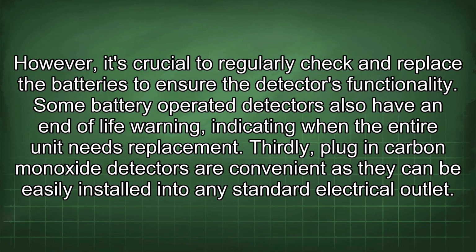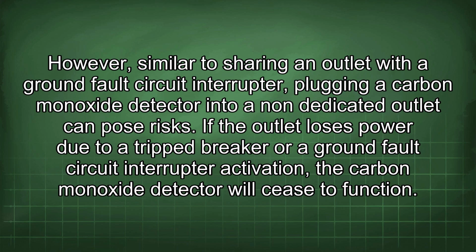Thirdly, plug-in carbon monoxide detectors are convenient as they can be easily installed into any standard electrical outlet. However, similar to sharing an outlet with a ground fault circuit interrupter, plugging a carbon monoxide detector into a non-dedicated outlet can pose risks. If the outlet loses power due to a tripped breaker or a ground fault circuit interrupter activation, the carbon monoxide detector will cease to function.